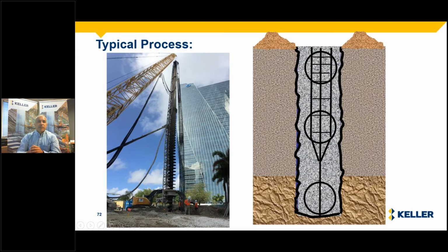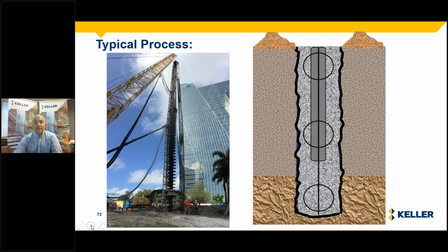So there's a couple of minutes between the completion of a pile and the installation of the cage that should be performed. That reinforcing can be done with reinforcing cages. It can be done with beams, I-beams, pipes, or so on. In some different parts of the world, a full cage to the bottom of the hole is requested to verify that the hole has been completely installed and is fully open, verifying that the shaft is complete, the integrity is complete. In other parts of the world, they are okay with just having reinforcing on the upper portion of that pile, just the upper third of the pile. So it depends on the local codes and regulations.